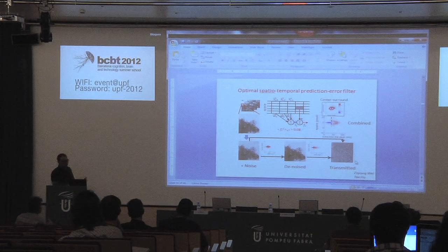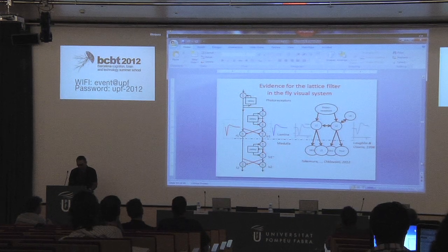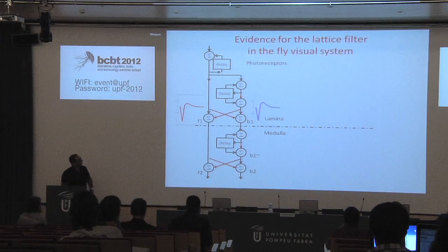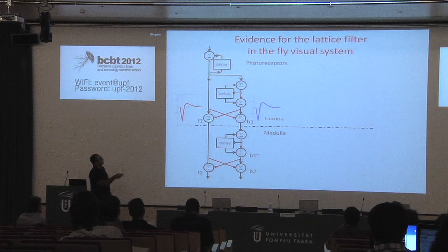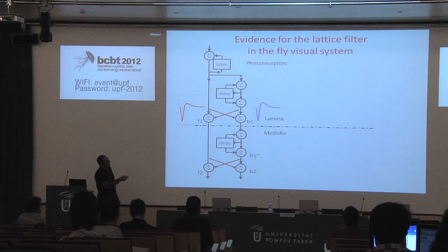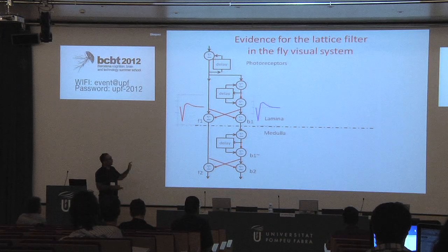How is that done? Again, inspiration comes from adaptive signal processing. And the way they do it is they build a lattice filter like this. And then if you tap that filter at this point, and also combine it with the original signal, you get an orthogonal set of features that are extremely good for using to predict another channel of side information.